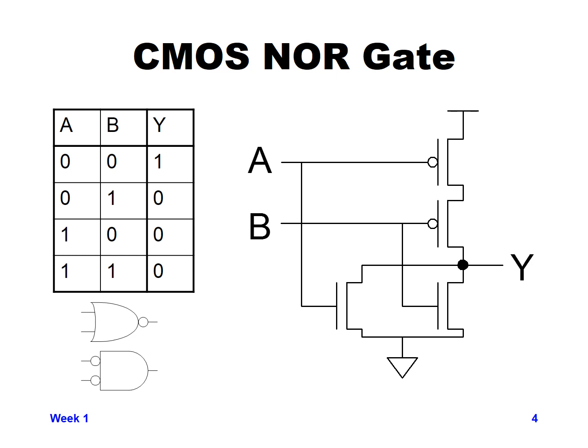function with the NOR symbol with the curved left hand side, and then the bubble at the output is for an OR gate inverted, an OR not, or a NOR gate. And then the bottom symbol, with the flat left hand side, is an AND gate symbol, but with the bubbles at the input, meaning that the inputs are inverted.